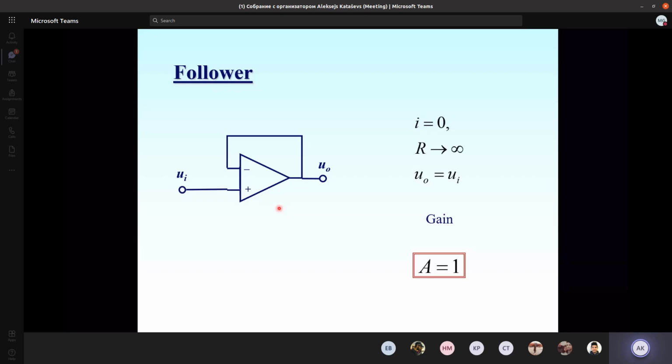But as an amplifier may provide more or less high current from the power supply, this follower could keep the voltage high even when the load, I mean the effective resistance switched between the output and ground, may be low enough. The real amplifier actually has an internal output resistance of about 40 ohms. And for the input of the next stage, up to 40 ohms, or even on the order of ohms, it's fine. It still could keep quite high voltage.